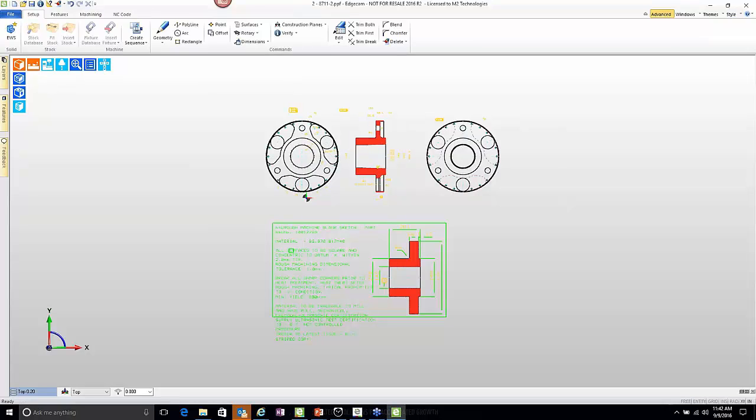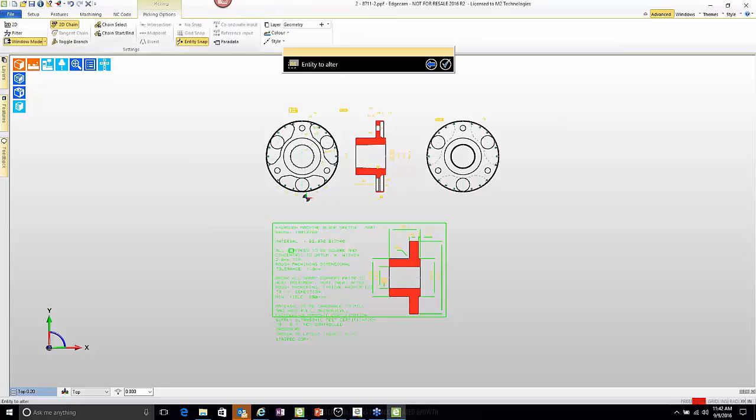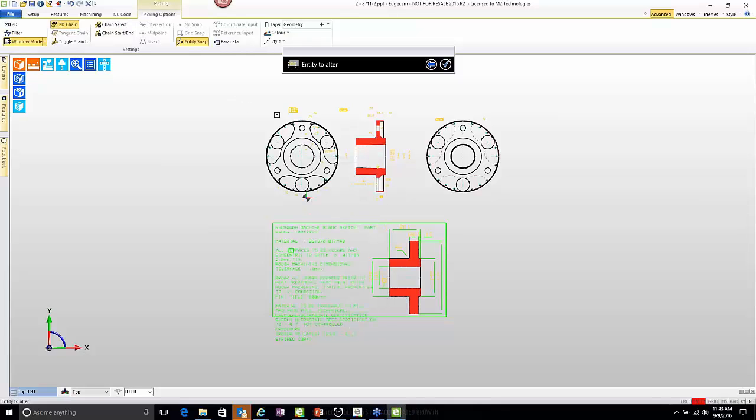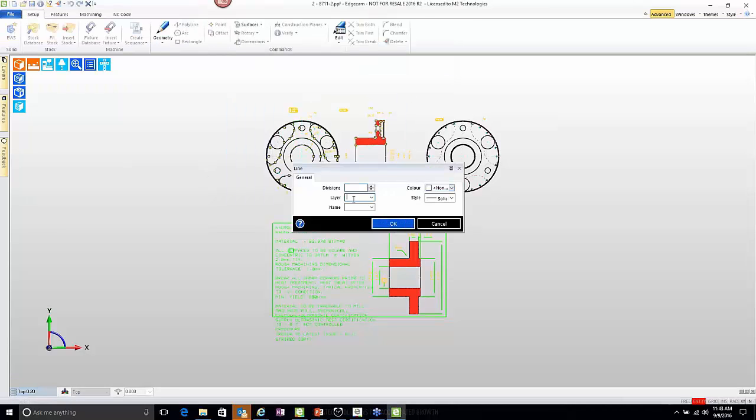Similarly, let's say that what I want to do is change the layer assigned to things, and so the layer assignment needs to be done to the things that are intense white, because I want to separate those from the other things. I can stretch a window. It only selects the stuff that is intense white. Maybe I move it to a layer called manufactured part.